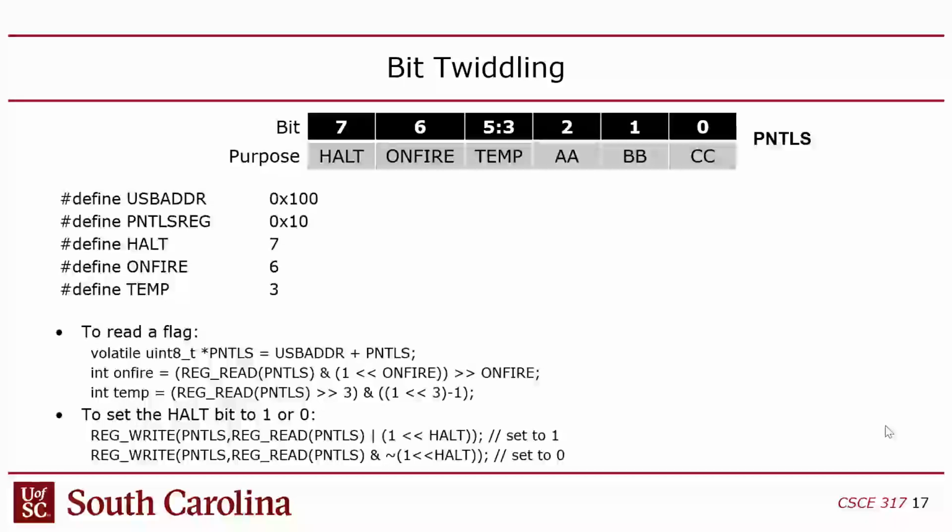So one option is you can take this pointer and dereference it to read it, right? Now here's the problem with that. That's actually the way it worked in the Arduino, the Atmel chips. But in other architectures that have a cache, there's an issue, because if you dereference an I/O address as a regular load or store instruction, that may get intercepted by the cache because the hardware may think that you're accessing memory, right? But whenever you access peripherals, you want to bypass the cache, right?